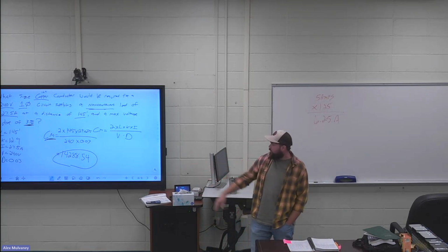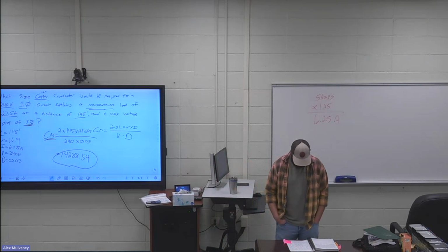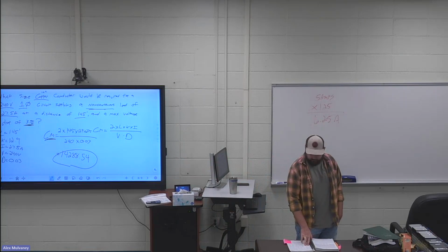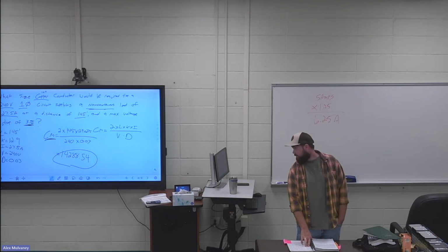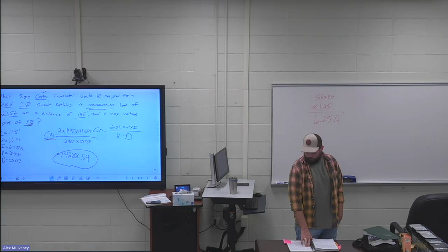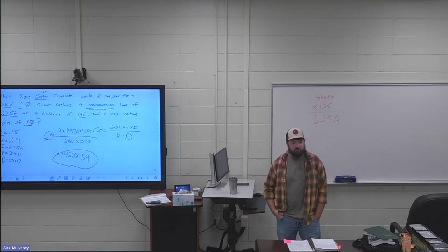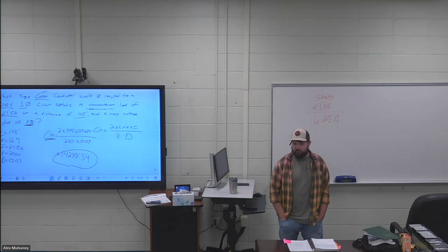So what size wire has over that amount of area? Oh, no, because that's 167,000. Right, we're looking for 14,000. 8, yeah. Why does 8 work? 16,510. Is that bigger than that? Yep. If you go down to 10 gauge, remember 10 gauge is smaller. What's the size of 10 gauge? 10,380. Is that big enough? No. So you have to use 8 gauge wire.